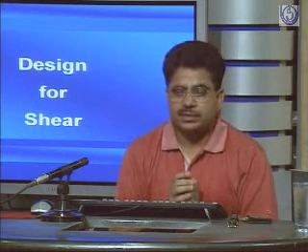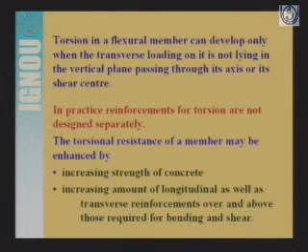In practice, reinforcement for torsion is not designed separately. It is a very important statement here that we are not going to design the reinforcement for torsion separately. Then the question comes, how do we take care of this?